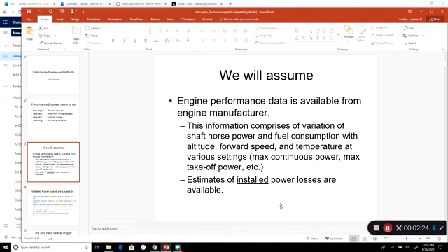But what happens in the case of helicopters is the engines are buried inside the fuselage. So you have a large inlet through which air is pumped, and usually a large outlet or a duct through which the hot gases come out. Once you install it inside an airframe, things change.